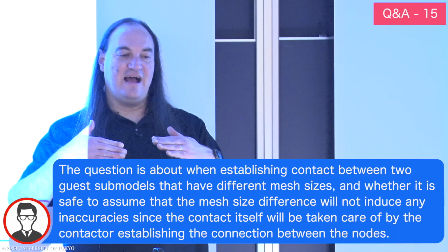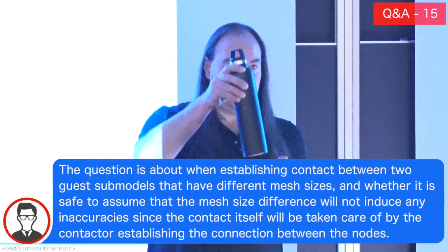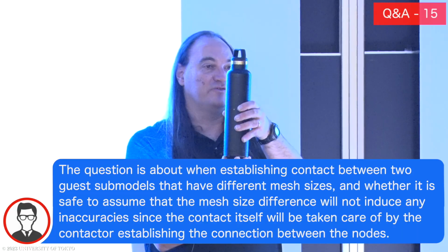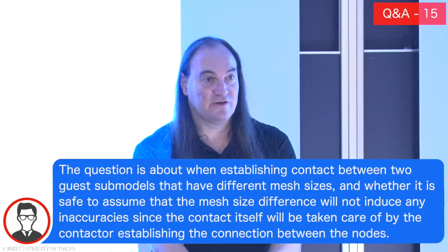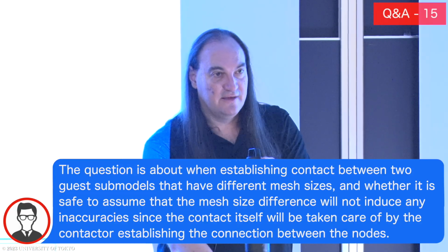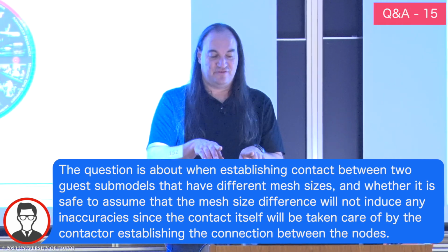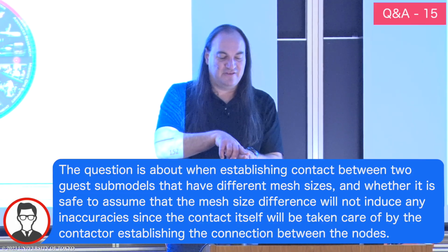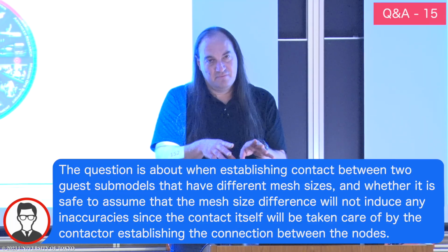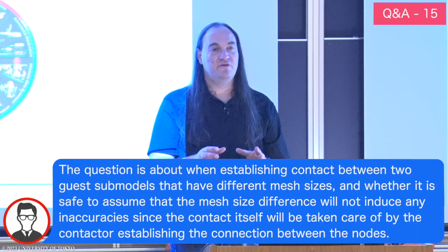So a contactor will take and subdivide the surface. If I have this contacting here, it's going to take this and divide it into 10 by 10 small surfaces. Here it's going to look and see which of these tiny subsurfaces projects onto the node areas associated with the mesh underneath it. So yes, it's possible to get some places where two things line up and it might straddle a division between two sub areas, but it's generally close enough for our purposes to not be a problem.